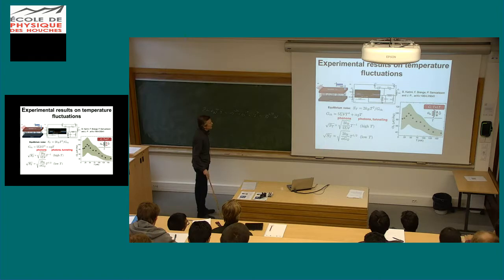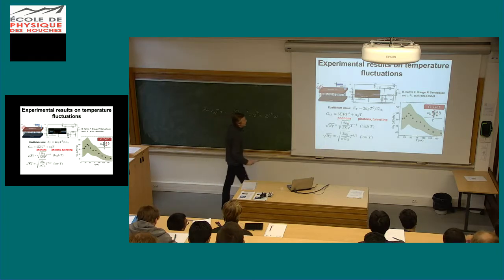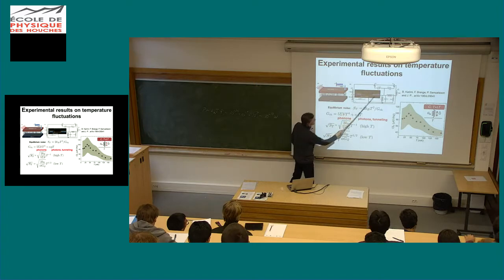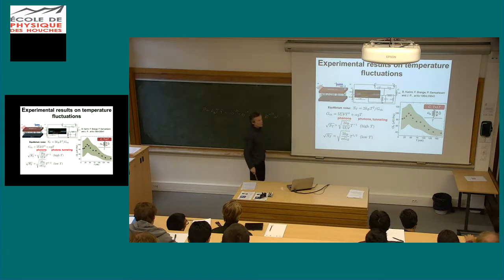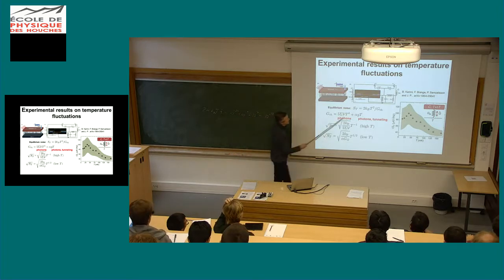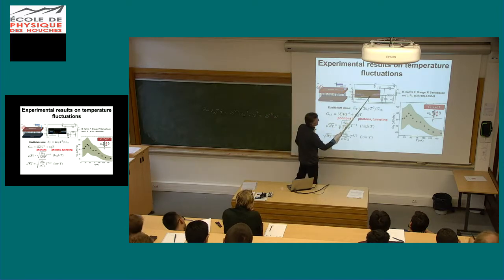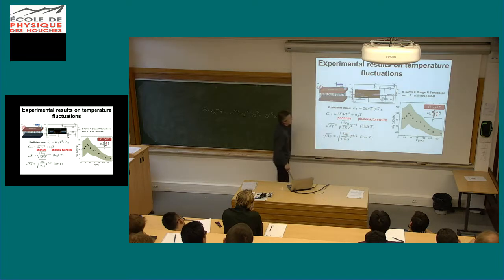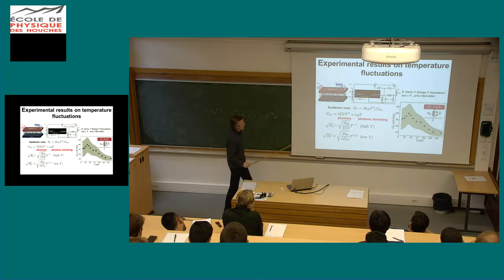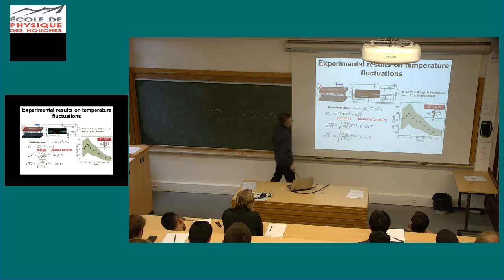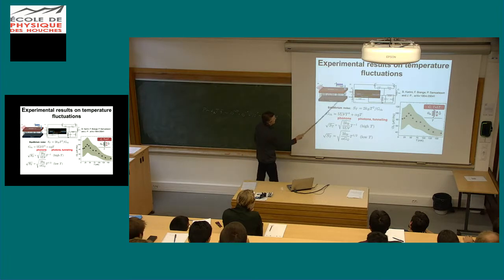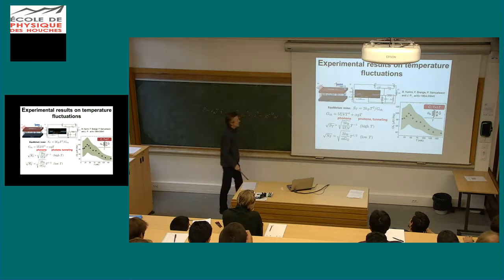Here are some preliminary measurements of that. We have exactly this setup, this absorber here, and we measure its temperature by the same thermometer which I explained to you, this conductance measured in this tank circuit at 600 megahertz driving frequency. We measure this noise only up to a bandwidth of 10 kilohertz in this case. So we have this absorber, connected to the bath, with electron-phonon coupling there, and then we can make, for example, time traces of this temperature.